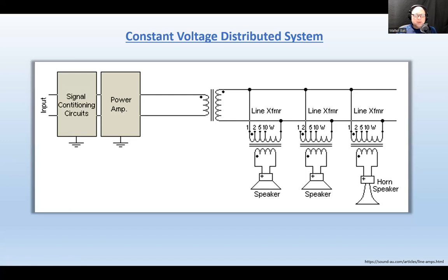The efficiency of the power transfer of the transformer is in the range of 98%. Right. And just as a reminder, what do transformers transform? Transformers transform voltage, transformers transform current, and transformers transform impedance. Hence, there's the idea of something called impedance matching transformers. Well, these could be used as impedance matching transformers because it matches the high impedance of that main bus line to the low impedance of that. So the impedances are transformed.